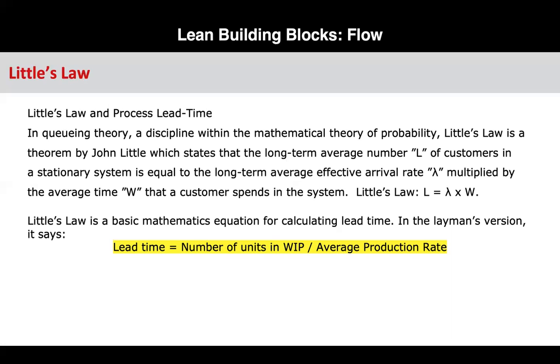That's the reason you hear, in lean terms, single piece flow. But we just showed that when you incorporate material handling, one piece flow is not the best way.